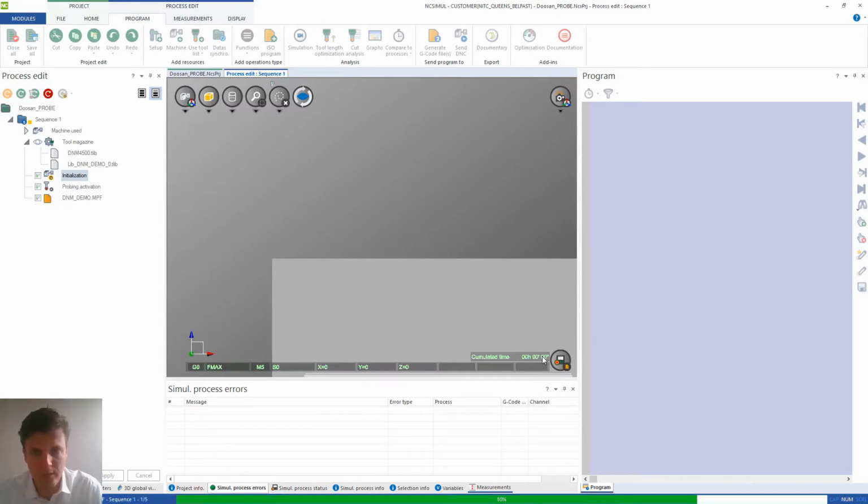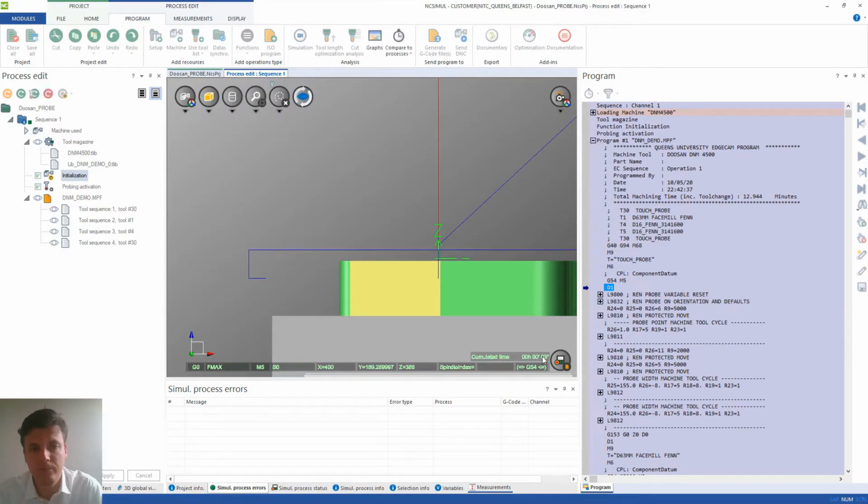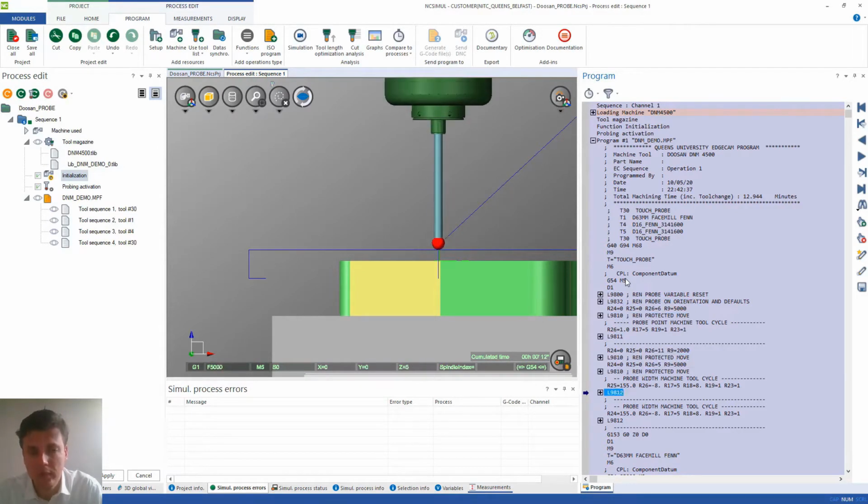You can see the difference soon on the screen. The z-axis is actually 1 millimeter above the surface. So you can see that now. Let's use the arrows. It positions the tool there. First hit, second hit, and once it's positioned back, hop, the z-axis is corrected again.